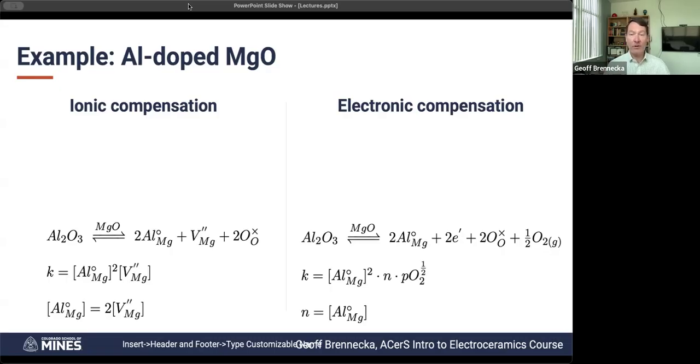Maybe you cool it down over the course of 2 days. But the kinetics of whatever process that was are still so slow that you never get to equilibrium. So you've frozen in that higher temperature state. If that kind of thing weren't the case, then we wouldn't have glasses, right? So there are a bunch of different ways that you can kinetically hinder something and essentially quench it. And so keep in mind that a lot of times we will sinter things at 1200, 1400 C, and then we'll cool them down. It doesn't really matter how fast we cool them down on an absolute scale.